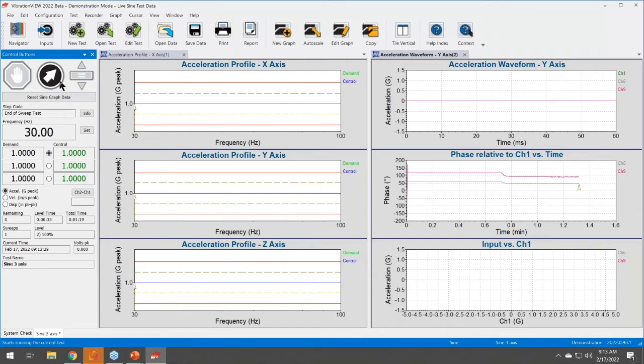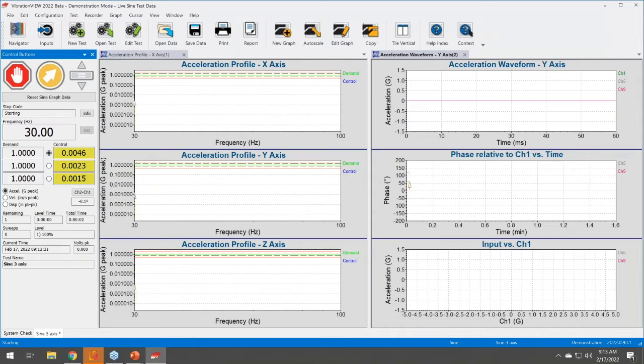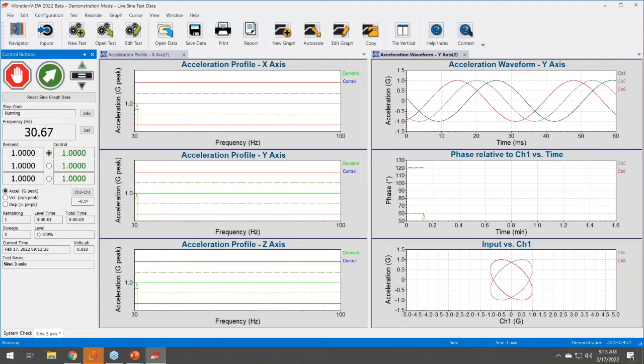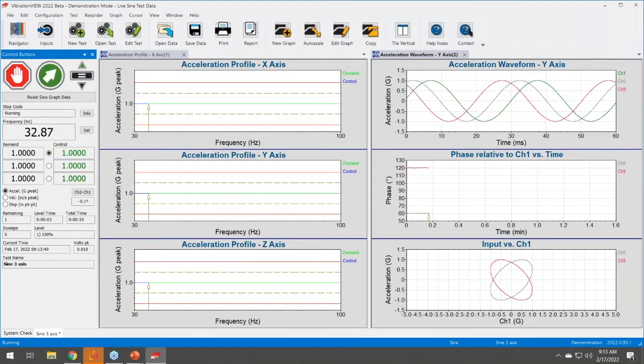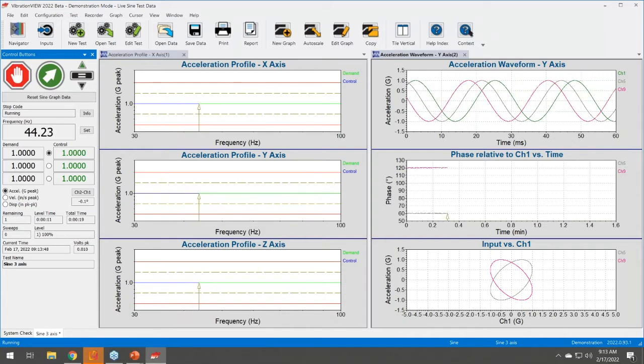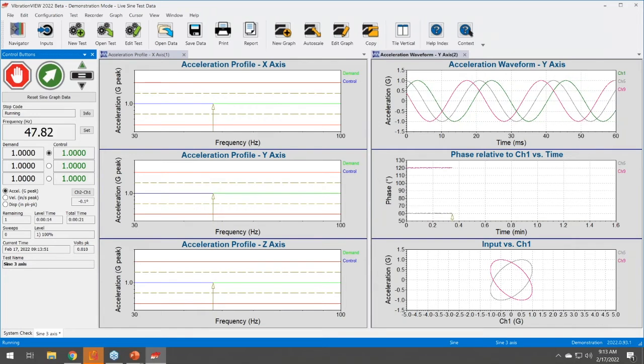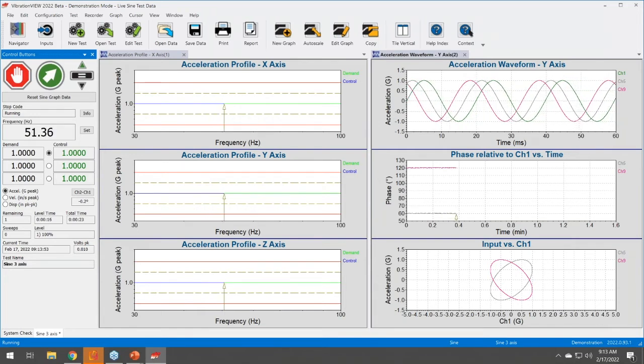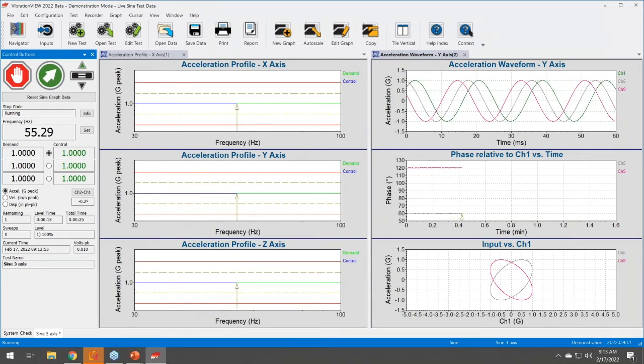And if you run all 3 axes at once trying to accelerate your test, you may end up not actually testing the axis that you are intending to test. So I guess something to think about, and check your specs if you are trying to accelerate a sine test using multi-axis.